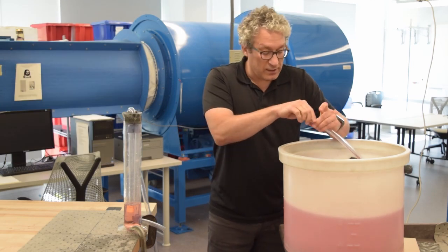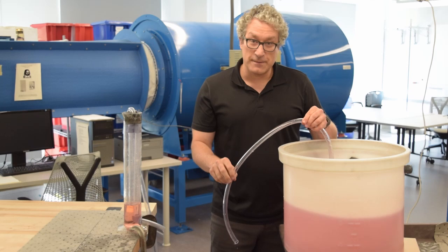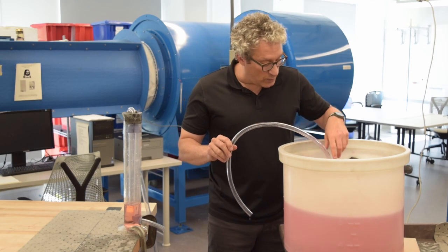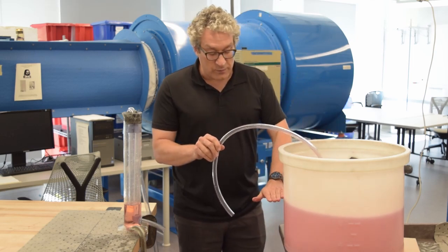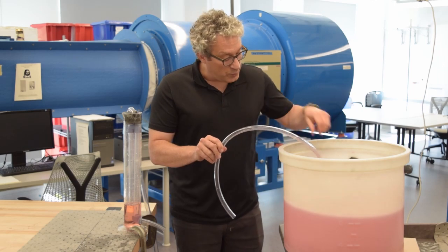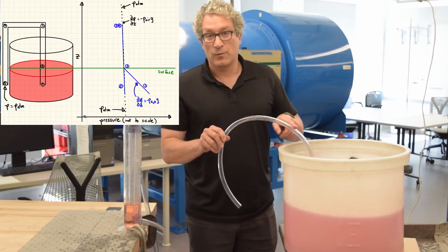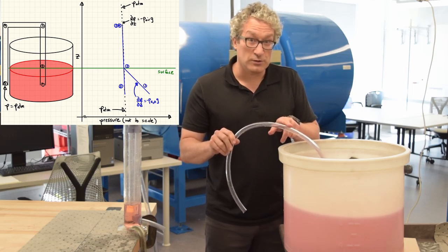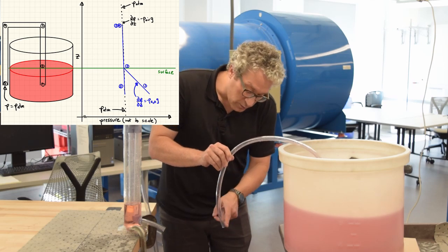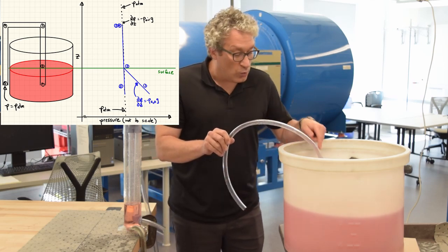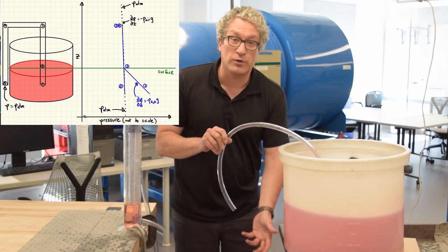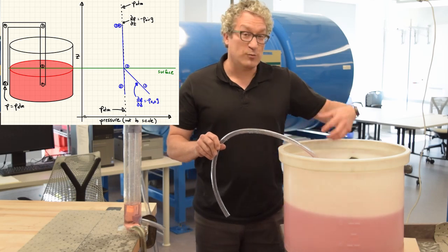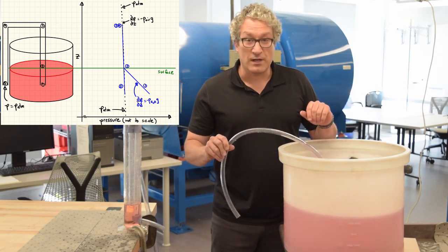Now I can't do the same thing if I lift this up and I just hold it like this, because what's inside the tube is air. So the relevant hydrostatic equation calculation tells me that when I start at the surface of the water, I have atmospheric pressure. Now the pressure as I move up the tube is going down, but it's going down proportional to the density of air, which is 1,000 times smaller. There's no way for me to create a pressure difference that's going to drive fluid through this system, because I'm using height differences with air, which generate very small pressure differences, and I'm trying to use them to move water, which is 1,000 times denser.